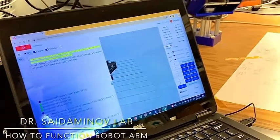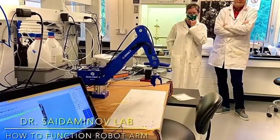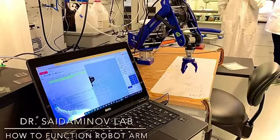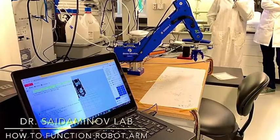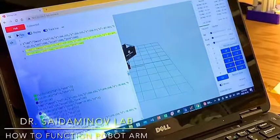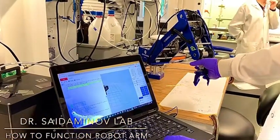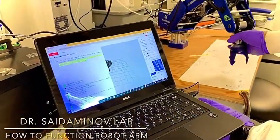So what is the difference between them? The velocity is meters per second, acceleration is the rate of change of velocity, and jerk is the rate of change of acceleration. So we can smoothly move the robot arm and measure with the spectrometer. Once we are done, we can click on the spectrometer and turn it off, and then halt the robot arm. But we have to make sure that once we want to turn off the robot arm, we hold it and then turn off the motor. Otherwise, it's going to be loose and damage the robot arm.